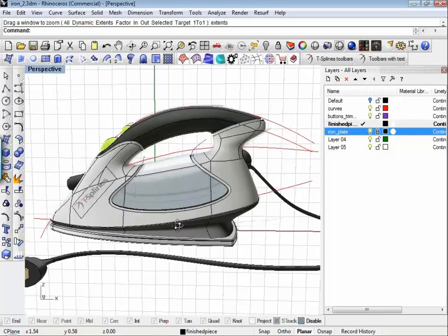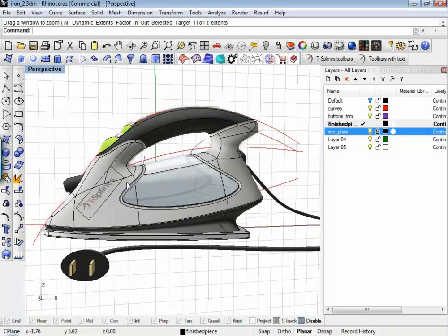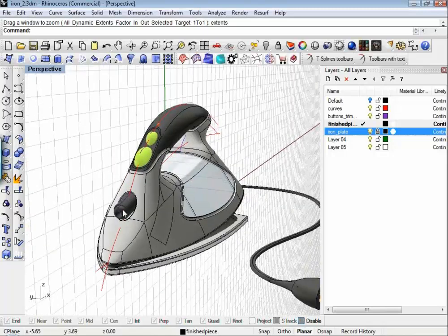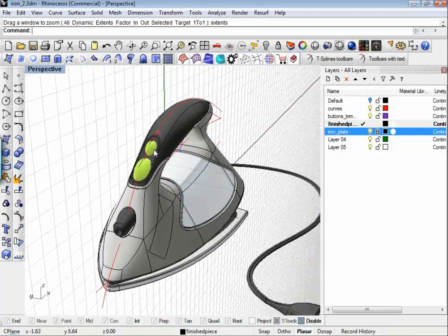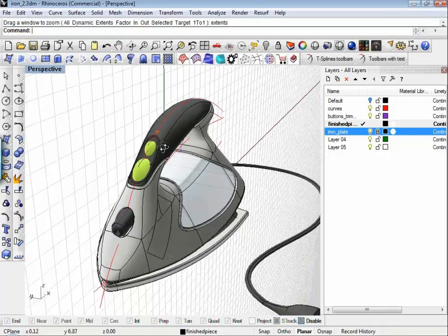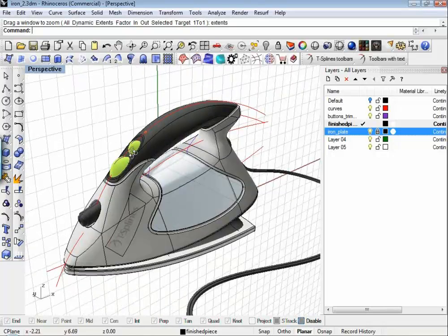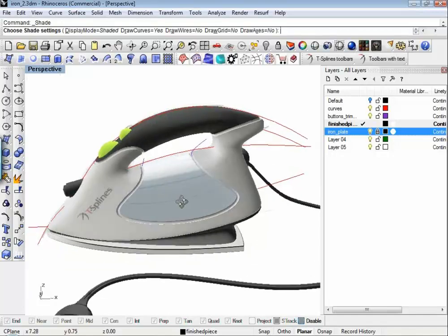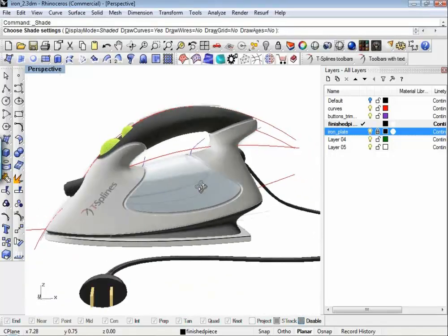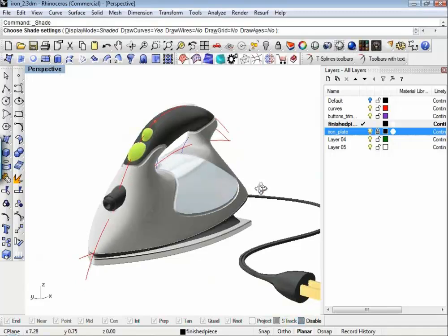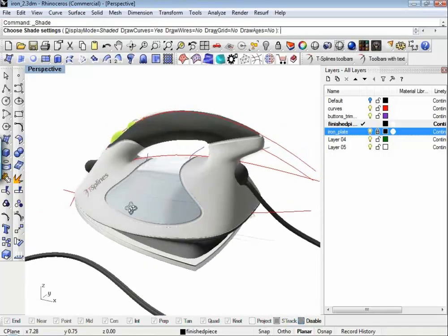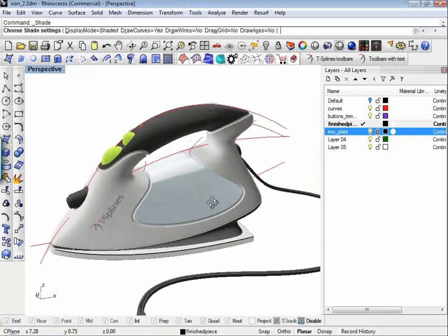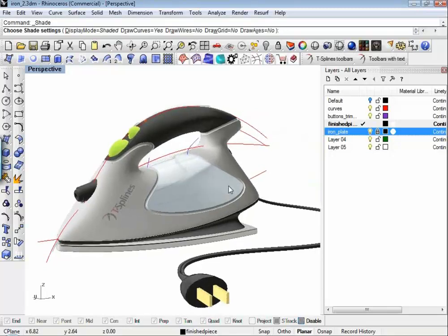Bring up my plate again. All I did was project curves onto this, Boolean this out, separate this. You know, I Booleaned out a sphere here, Booleaned out a single plane here, added all that stuff, and T-Splines base surface, Rhino detailing, a little bit of Oxpecker shader, and you're done. And here we are 39 minutes later with a finished product.